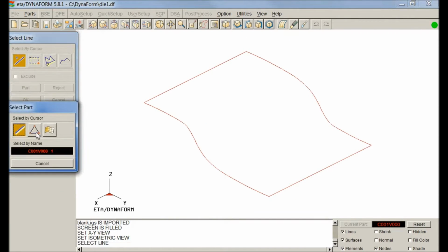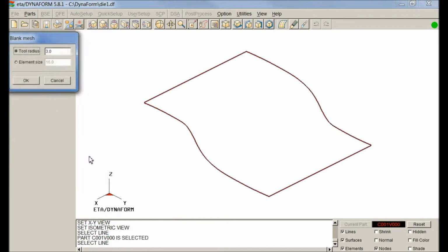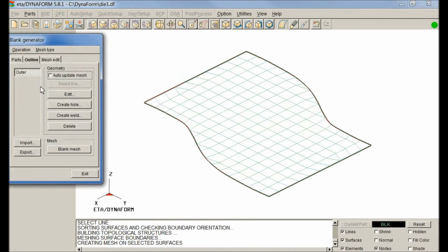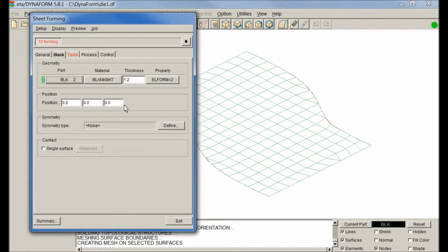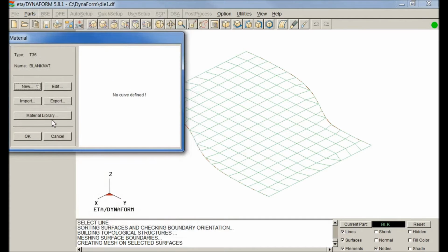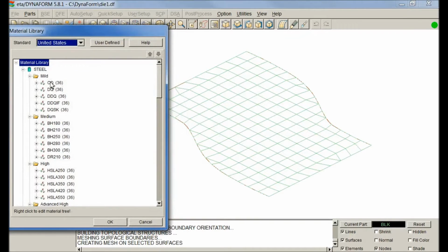And then I'm going to go ahead and mesh it. And that's a very important step in any FEA analysis. That actually is breaking the part up into these small pieces, and then for each piece the simple-ish equations are applied to them over and over to get our results.